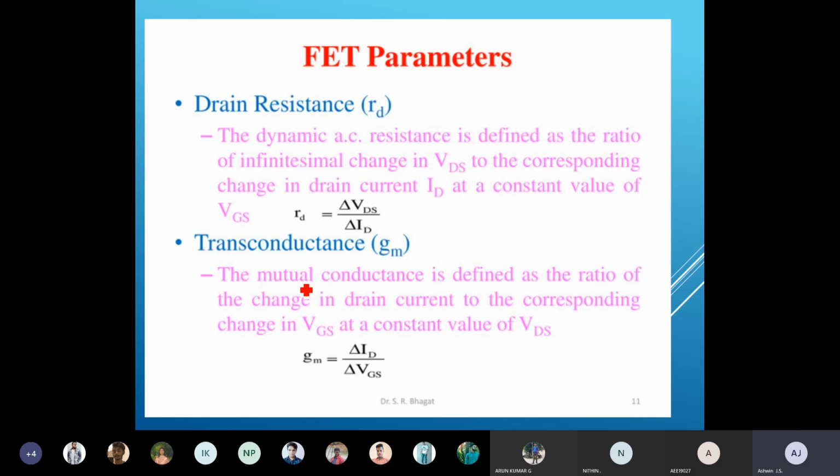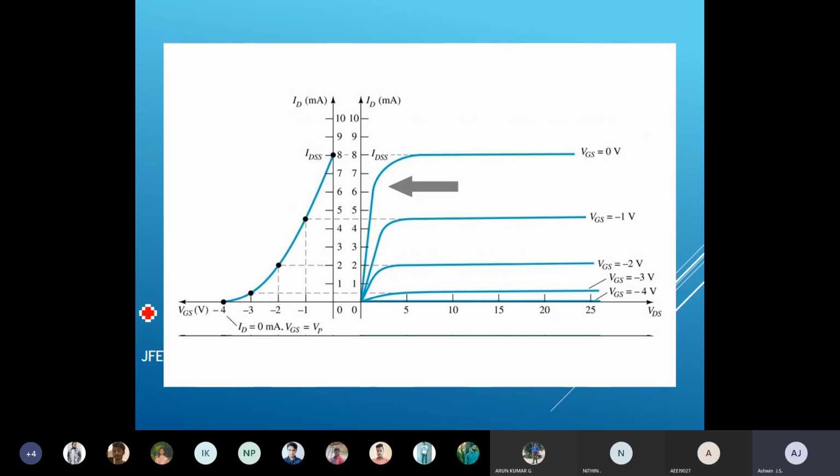So this is going to be calculated from the drain characteristics. So go to the drain characteristics. I'm going to take any two voltage levels which are available in VDS, and I'm going to observe what is the corresponding current. So for example, I will take these two values. Okay, so two values I'm going to plot. This may be around 2, and this is your 5. Okay, and I'm going to observe what is the current here.